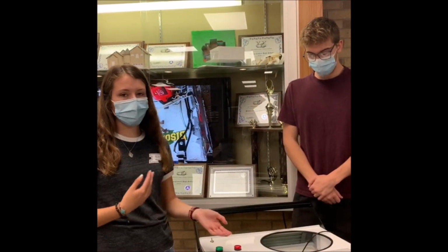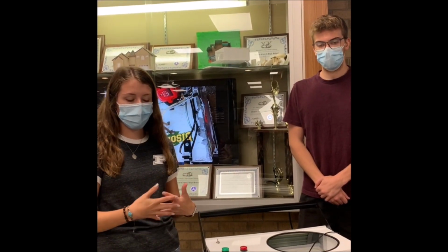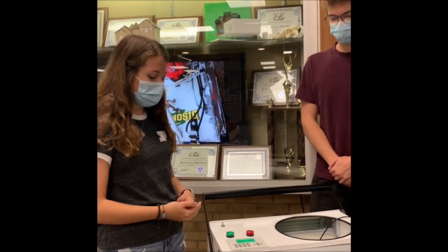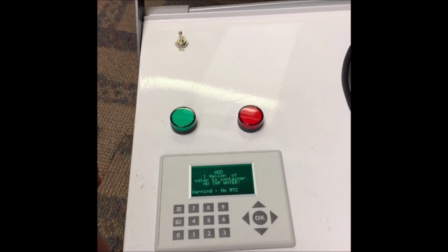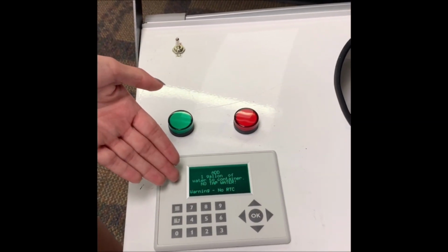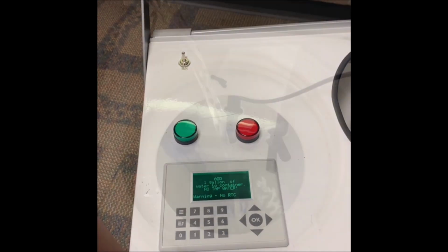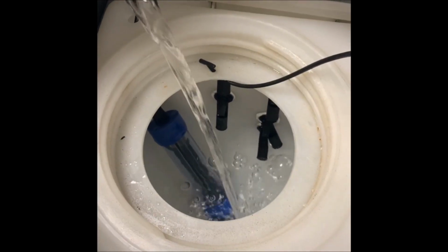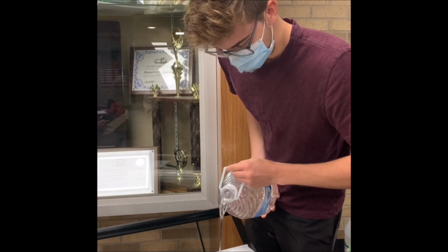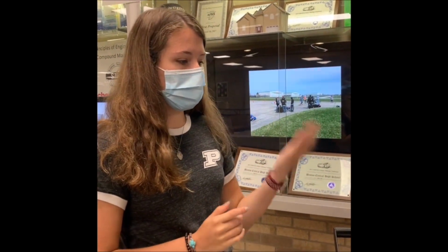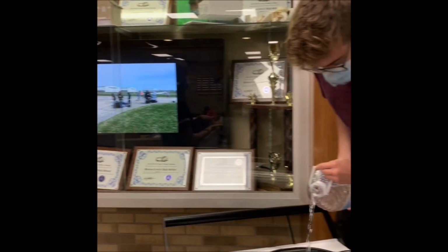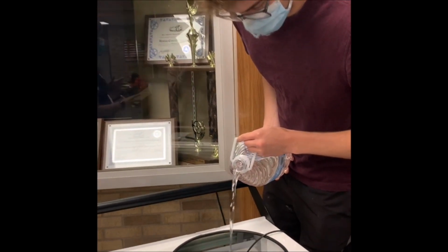So now we're going to show you how you make an HOCl cycle, a generation cycle. So we're at the options menu, so now we're going to press 1 to start an HOCl cycle. So now it's asking you to add 1 gallon of water to the container, which Evan and Logan will now do. It asks you to add the 1 gallon first, and then you will add your necessary salt and vinegar, because we found that if you added the salt and vinegar first, it would fall down into our pump and wouldn't get properly agitated and mixed into the solution.